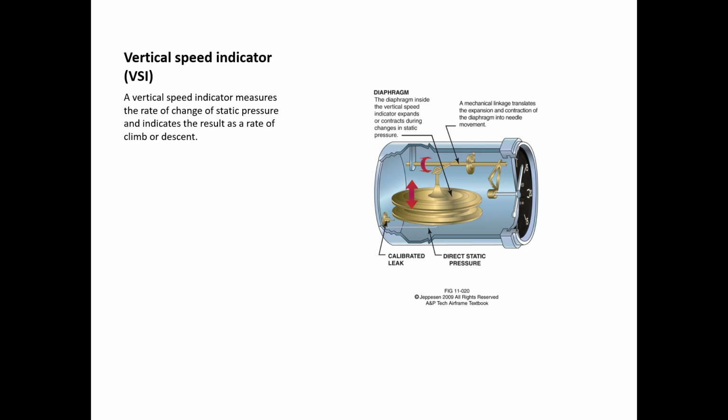And since it's a leak, it must be that excess air pressure is relieved out the side. Which makes sense, because otherwise it would just say that you're continuing to climb, but once you level off, the bellows would have an opportunity to contract as the excess pressure is relieved through the calibrated leak. All right, I guess I never looked at it that closely.